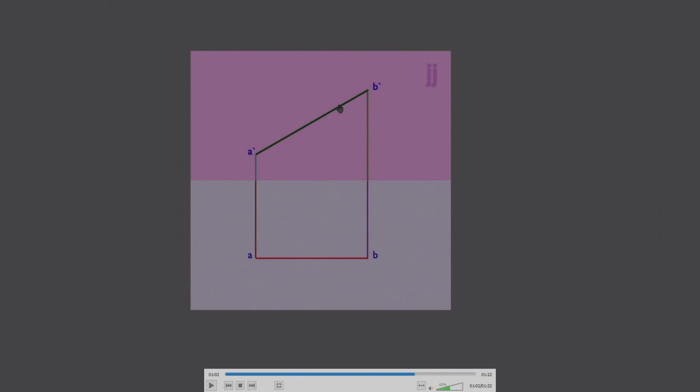The reason was that the line is parallel to the vertical plane and inclined to the horizontal plane. As you can see the inclination here, right? This is an inclination. Sorry, I told it the other way around. The line is inclined to the horizontal plane and parallel to the vertical plane. And since it is parallel to the vertical plane, the front view will give you the true length. So this is the actual length and this is a shorter length, right?